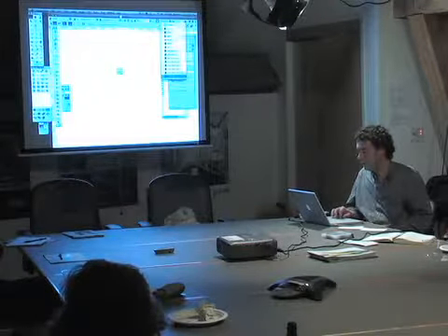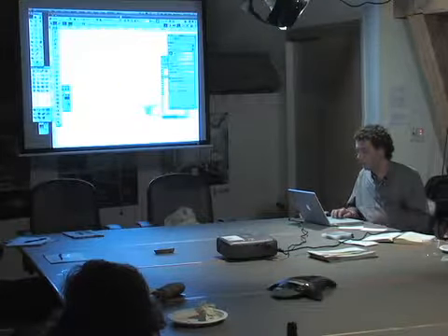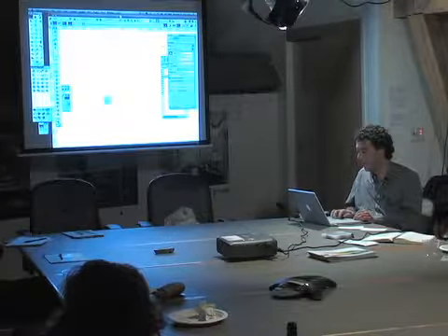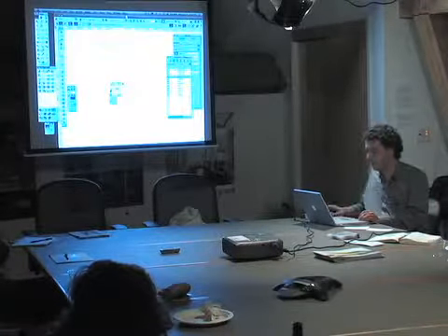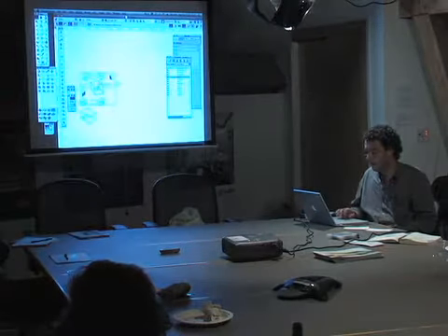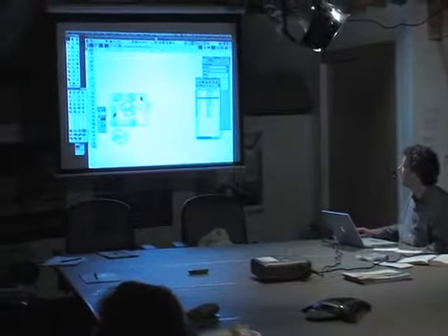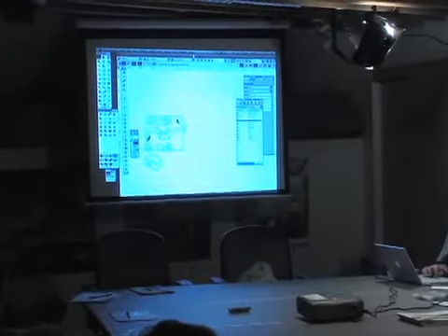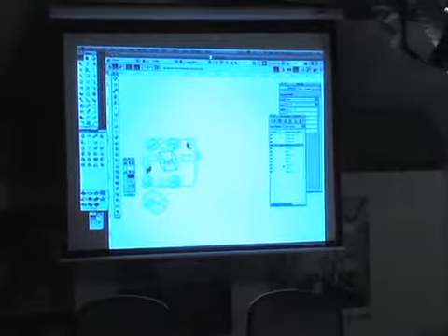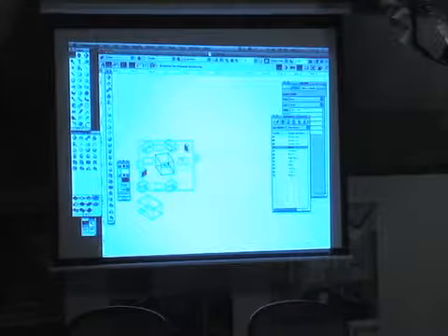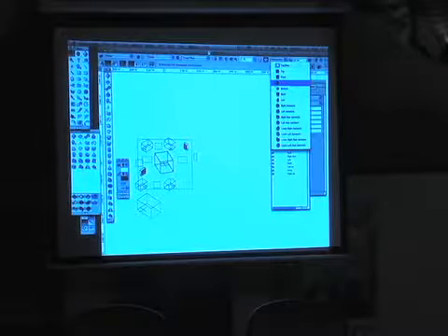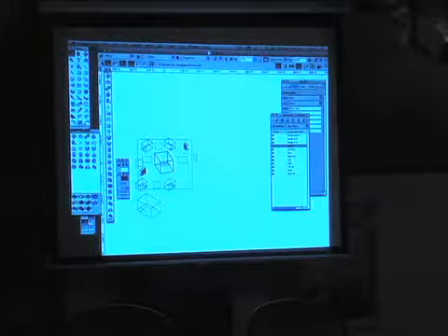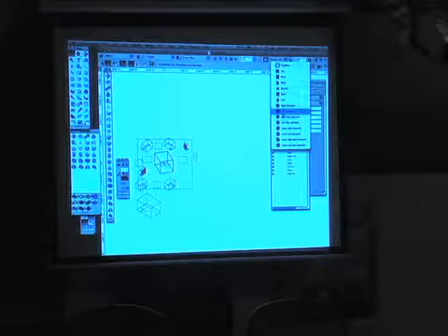I'm going to give this a lower left axonometric view, so we're looking at it from the bottom. And now go back to my show others, make my model active. So here I am working on the model layer, but I have all these other layers turned on that I've assigned these viewports to, and in each layer I've set the orientation up here, from the top, front, right, back, bottom, right isometric, and then I cut a couple sections. So each layer has its own orientation set up through this dialog box.